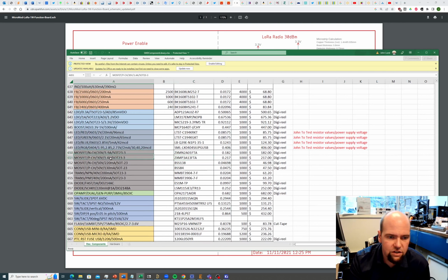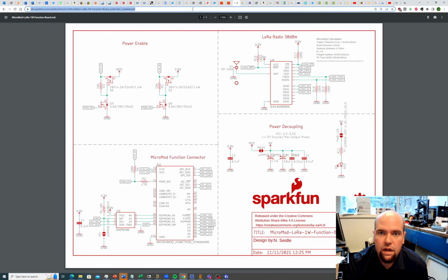Our power transistors are rated 1.9 amps and 1.4 amps, which really cut those currents in half if you want to know the actual current you'll be able to pass through them, which is fine. That should be okay. Our N channel is this one right here, and our P channel is this one right here. When we build these, we want to be very careful to choose the right footprint, because the order of source, drain, gate matters depending on the part. So if we look up this particular part, let's take this and copy it, and then we'll go back to